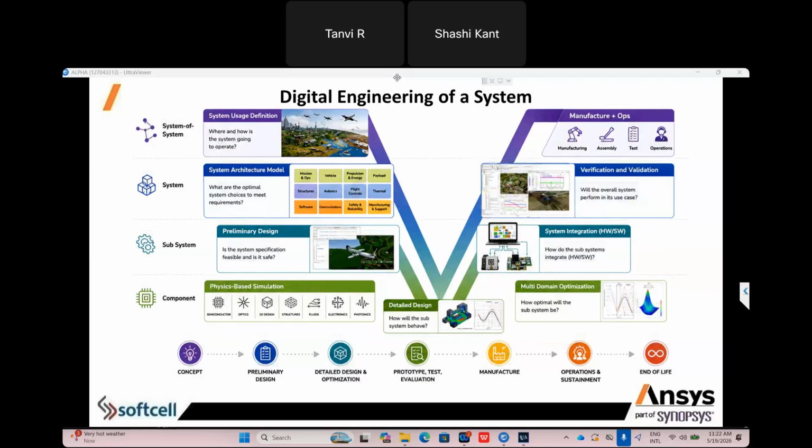Then we can see the real behavior of the pipe structure. So here we need to use multiphysics. We also have FSI, one-way FSI and two-way FSI, so we can integrate multiple physics to replicate a realistic setup as per the real scenario. The coupling can happen very easily, and then you can track results as much as the required outcomes.